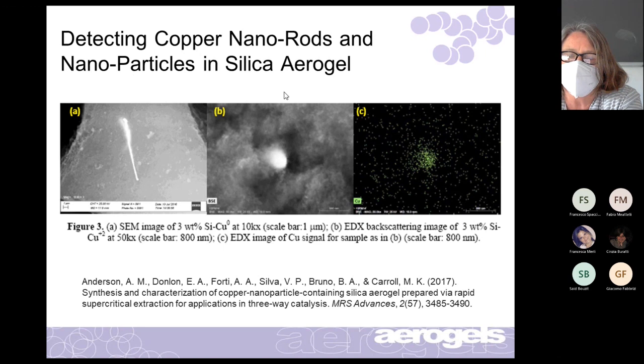And you can see, again, a little bit about the pore structure. We often do it just to say, yes, that's an aerogel, that it looks like an aerogel. But you need to get in very close to do that, and that's hard to do. By close, I mean you're zooming in. What happens as you try to zoom in further and get closer and focus is that because these things are so insulating, they get charged with the electrons, and then you get nothing. So that's a challenge.